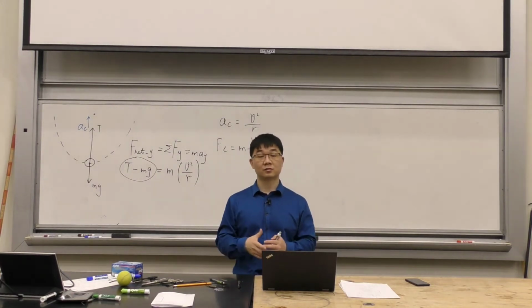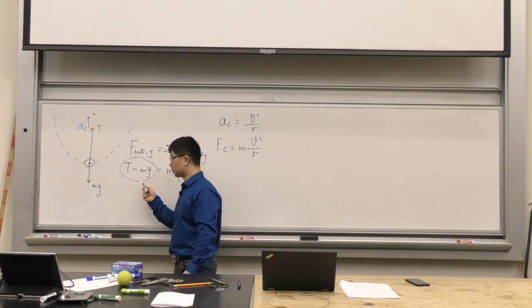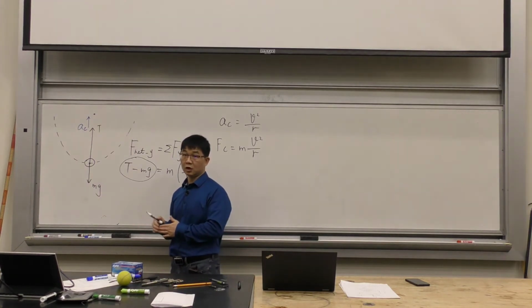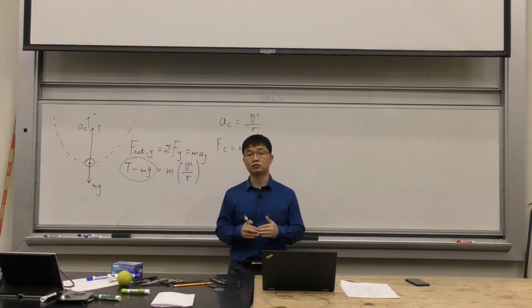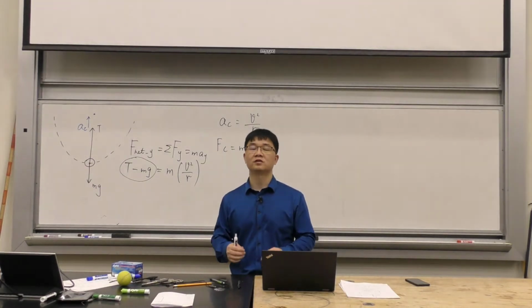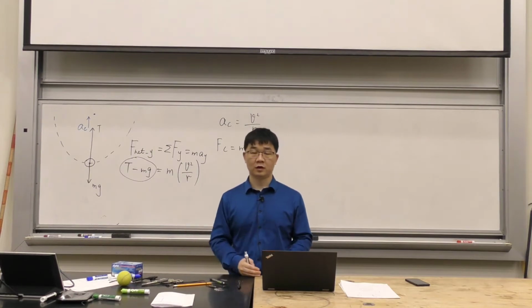Sometimes the sum, sometimes the difference, okay? In this case, the difference between these two forces is the centrifugal force. But I don't need to worry about that. I don't need to figure that out before I set up this equation. I always set up Newton's second law, because if anything is moving, it must obey Newton's laws of motion.